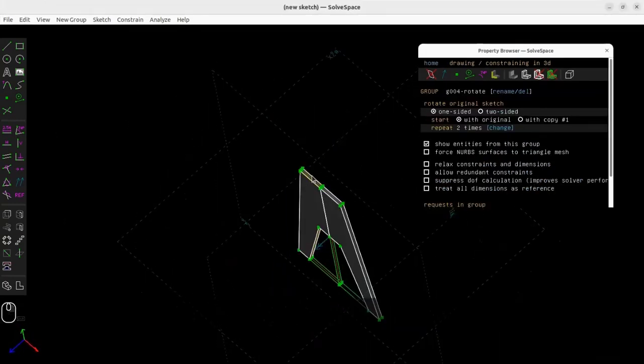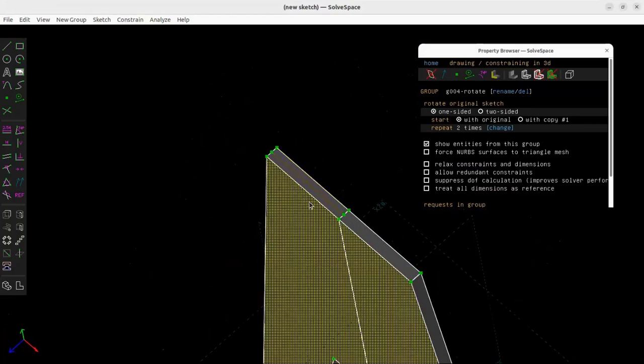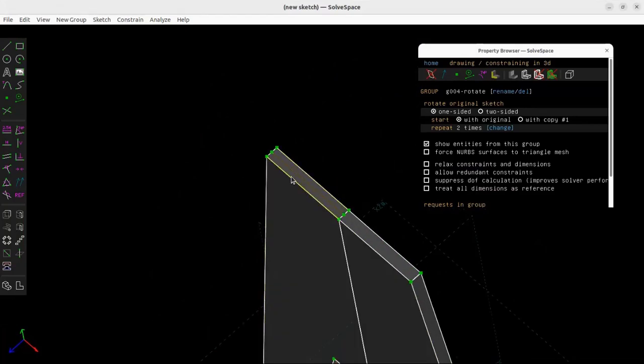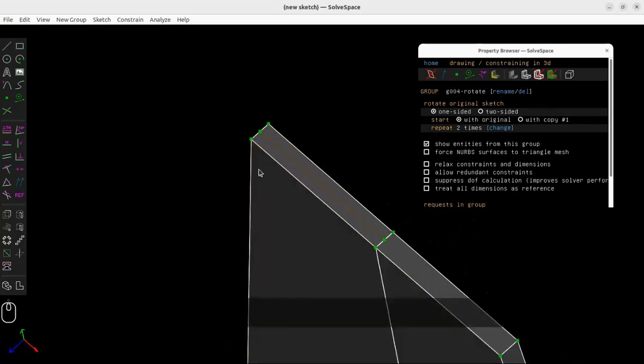Another thing is we want to use some form of finger joints in order to snap fit together with the surface over here. So we're going to create these finger joints that then fit into the pockets on the surface of the chair. In order to do so, we need to create a sketch in a plane, and before that, we need to create the plane, to define the plane.